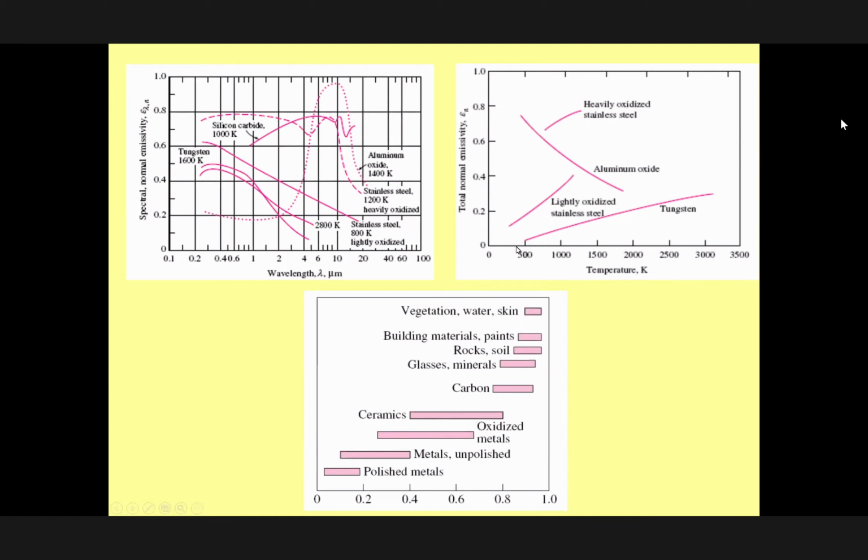As I mentioned, for most of the materials we're dealing with, in the wavelength range of thermal radiation, the emissivity is usually very constant within this value. Therefore, we can assume between 0.4 to 0.7 or 1 it is almost constant in our application. And if you look at the temperature here, we're dealing with very low temperatures, ambient temperature, 20, minus 20. Therefore, we can assume it's constant.